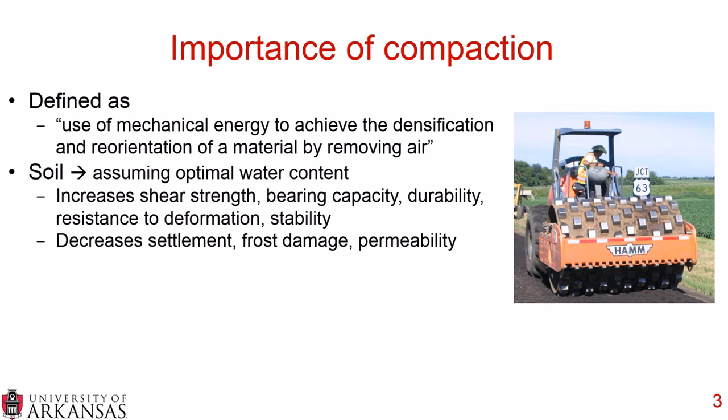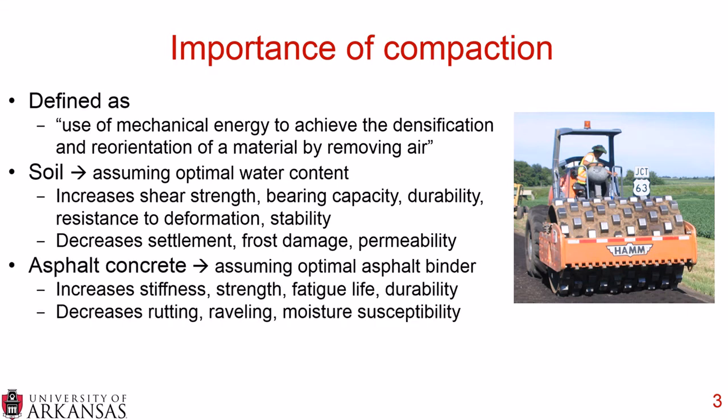Now, another common material that we need to compact in the field is asphalt concrete. And again, we're assuming the optimal asphalt binder content. When we're compacting asphalt concrete, we're increasing the stiffness, the strength, the fatigue life, and the durability. And at the same time, we're decreasing the potential of rutting, raveling, and moisture susceptibility.